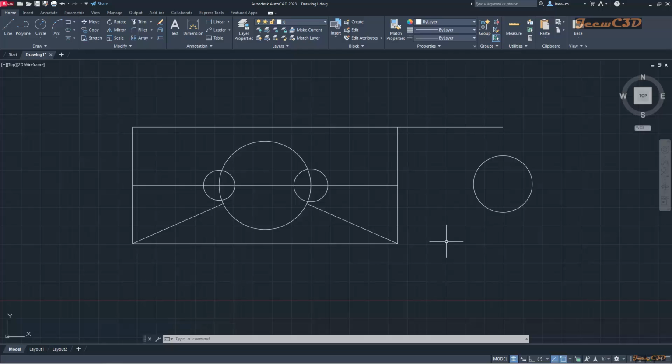To initiate the line command, I will press space bar. So I start from here. Now I am going this way. Now I have to get this center point. I am not clicking, just holding the mouse there. Now I am coming downwards. When the two snaps are connected, it will show me the point. So I will click here to stop the command. Then I press enter, or otherwise you can press space bar as well.